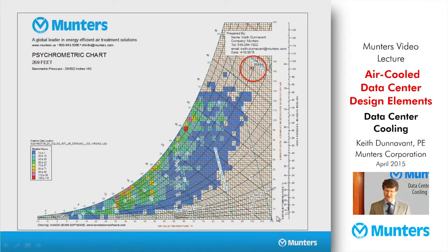At the very bottom, there's 0 moisture in the air, and as you move up, there's an increasing amount of moisture in the air. As you go higher up, you're getting finally to very high moisture contents, and you'll see that that 84 wet is really quite an extreme condition.